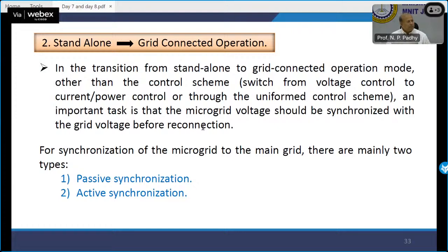When I talked to my family members, it was found there is no power and no electricity available in the home, even with distributed generation capacity close to 1.75 to 1.8 megawatt. Is it okay? So now the worrying part is why is this not happening? Because when the grid is not there, the DGs also stop generating power because they don't see any reference. A little bit of diesel generators could contribute. Now they're also off. So all the PVs have gone to sleep because they cannot generate any power.